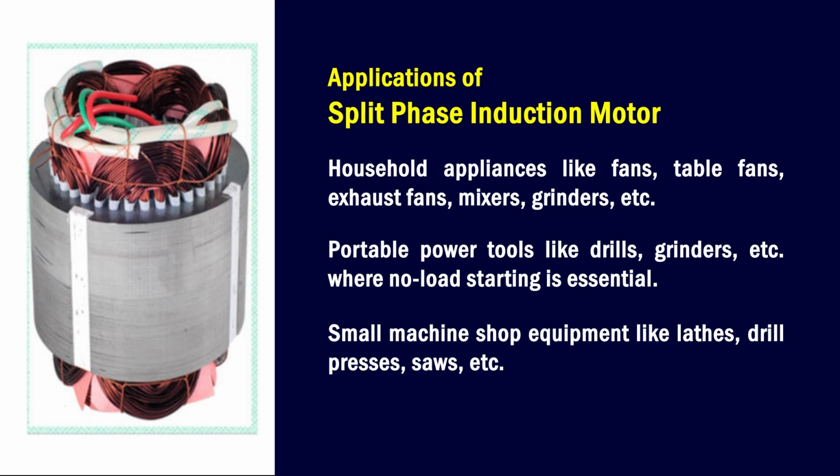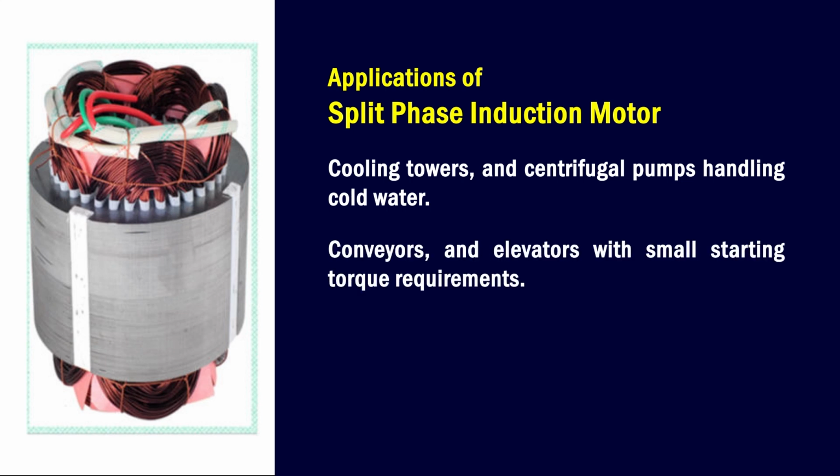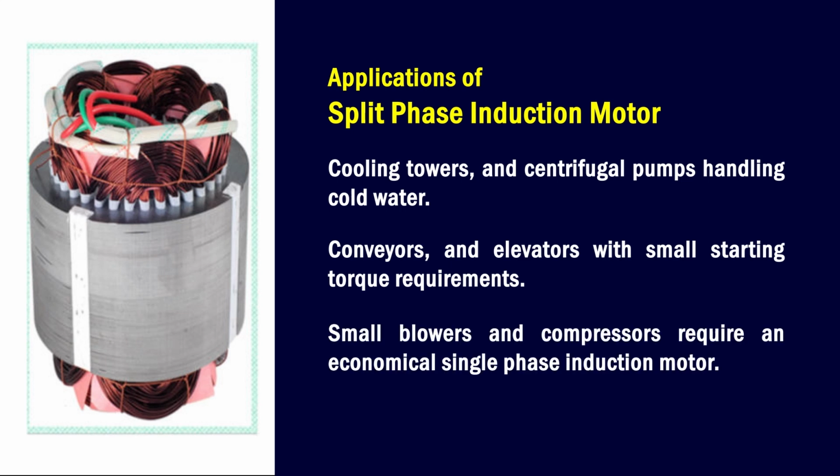It is used in small machine shop equipment like lathes, drill presses, saws, etc. This type of motor is used in cooling towers and centrifugal pumps handling cold water. They are used with conveyors and elevators with small starting torque requirements. This type of motor is used for small blowers and compressors which require an economical single-phase induction motor.